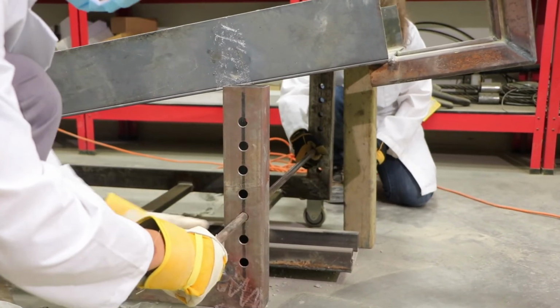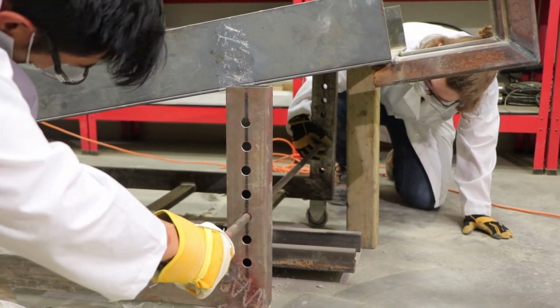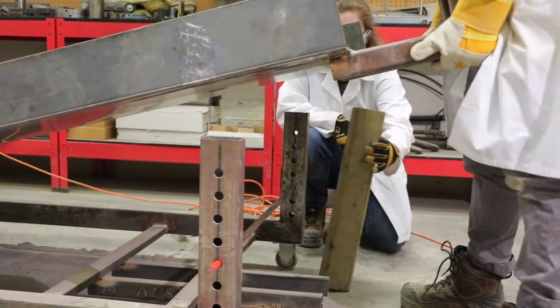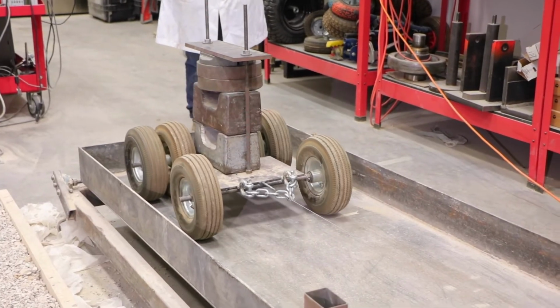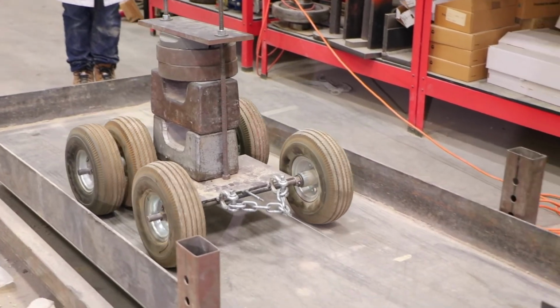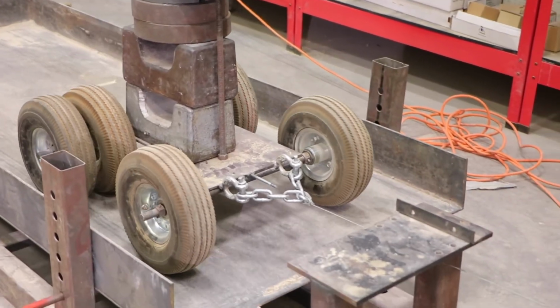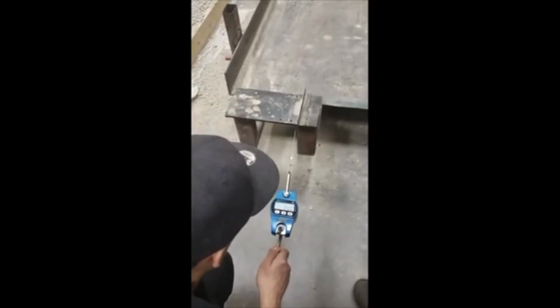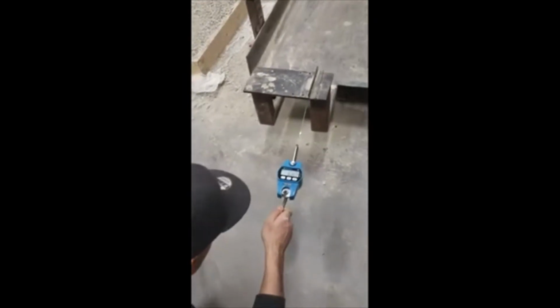Set the calibration bed to its first inclination and record the rise and run, then pull the vehicle steadily along the bed, keeping an eye out for the most consistent output force and making sure the cable is parallel to the bed. Repeat this pull test 3 times for each of the 4 inclinations, and find the relationship between rolling resistance and force using a graph.